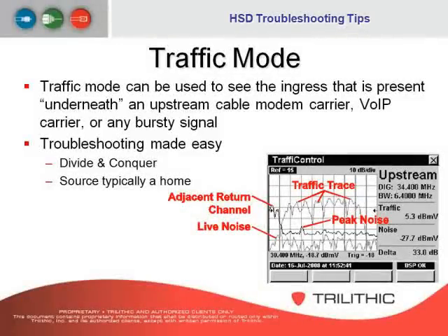It's important when you're making this type of measurement that you also set your reference level, because the reference level not being set correctly is what measures your input level that's coming in. You could actually overload the analyzer, and it can show you some beats or what looks like distortions happening in that particular carrier that may not even be there, but it's all because you're overloading your meter. And it'll actually show you on the meter if it's in an overload state. It'll show that it's overload.